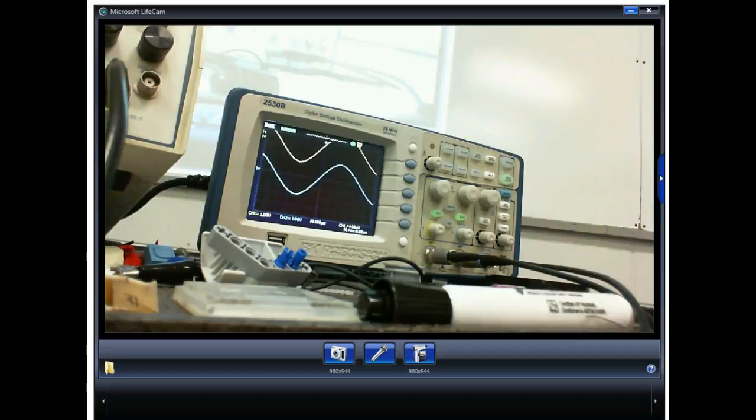Same thing is true on motor controls. When you get into motor controls, you start troubleshooting. You start at the load and then move back toward the source, and you're looking for your voltage. You're looking for your signals. When you find your signals, it's what you just went through, right? What you just went through has to be the problem. Are we okay?